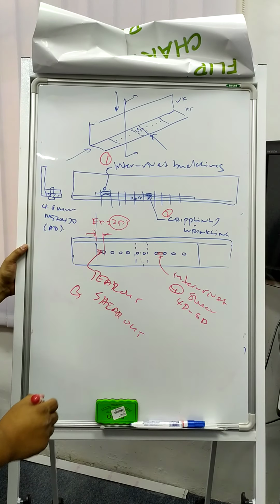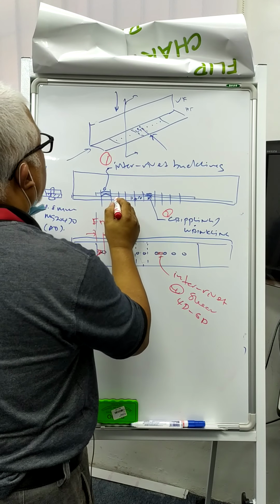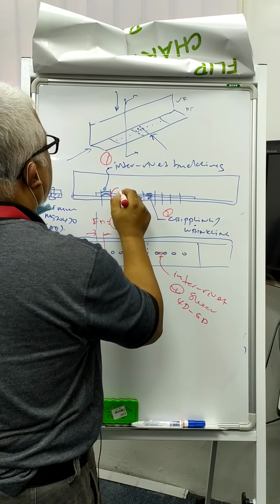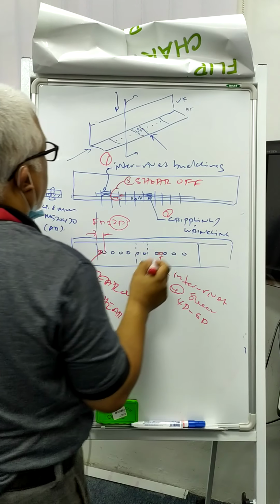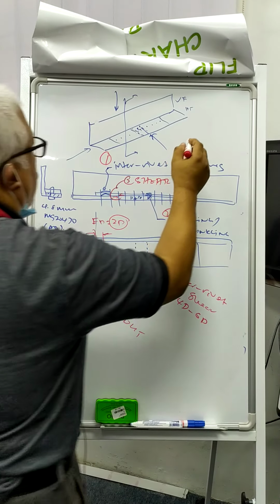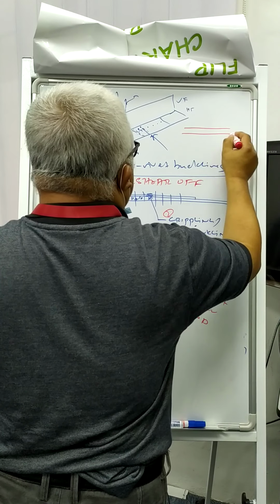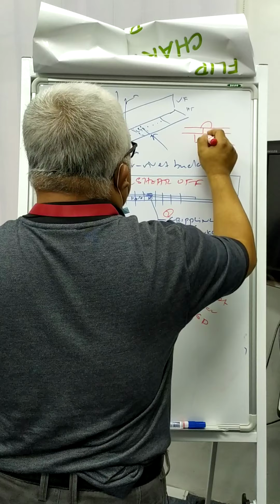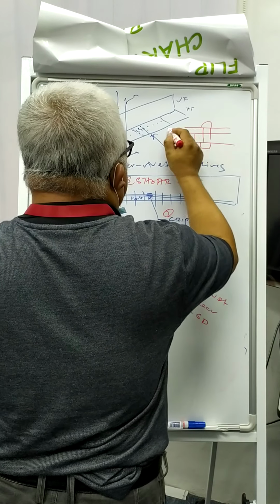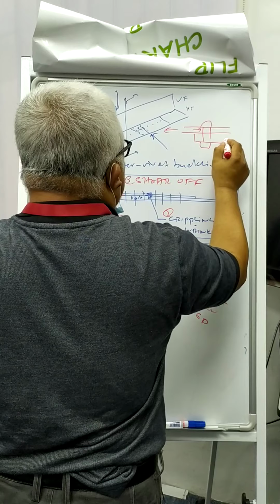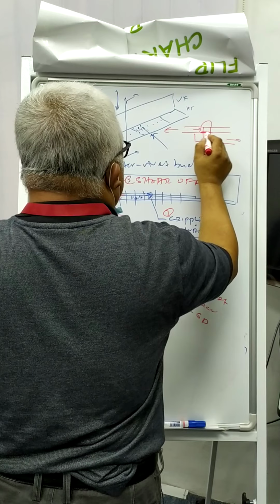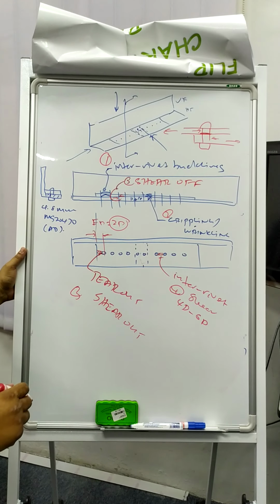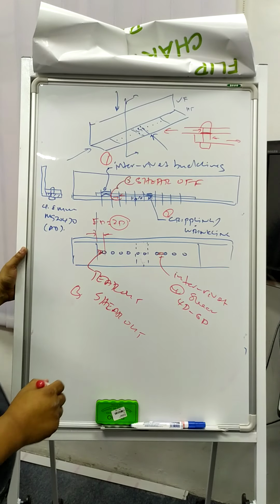Okay, another failure will be shear off the rivets. Failure 5, shear off. Mean the rivet cut into 2. So shear off case is we have a plate, and then we install rivets. So the force here will be against here, the force here will be against here. These two forces acting together, they may cut the rivet into 2. So that is another potential failure.